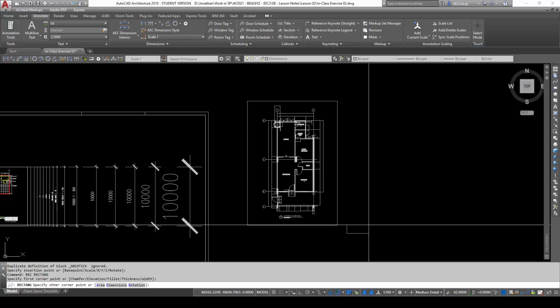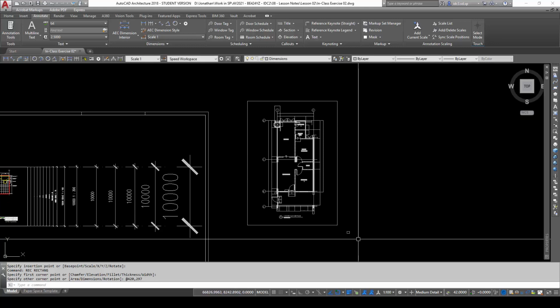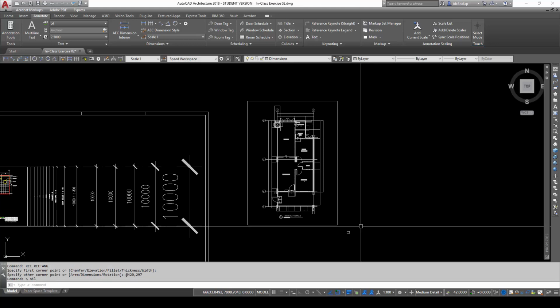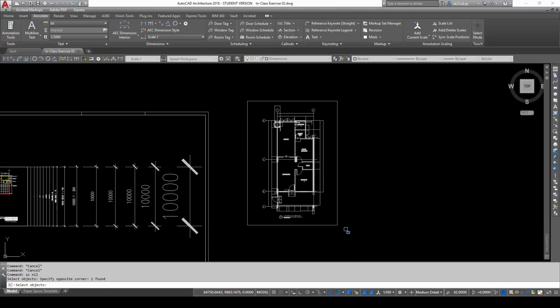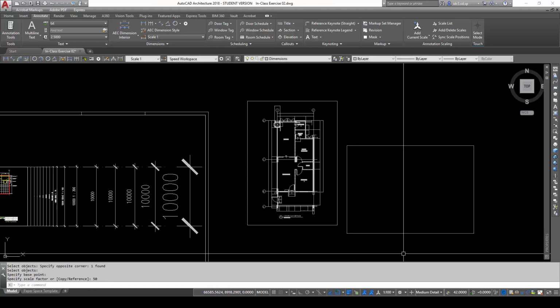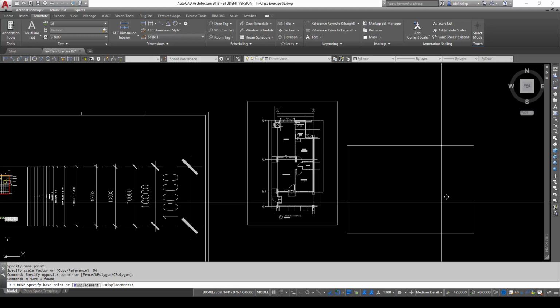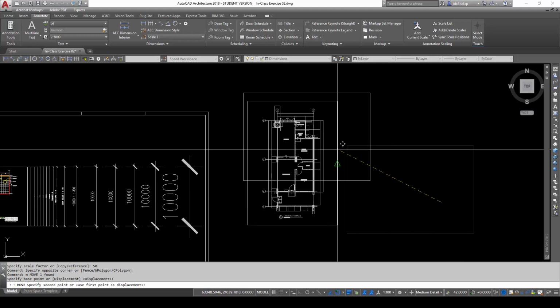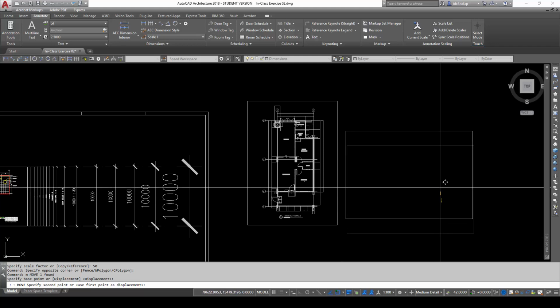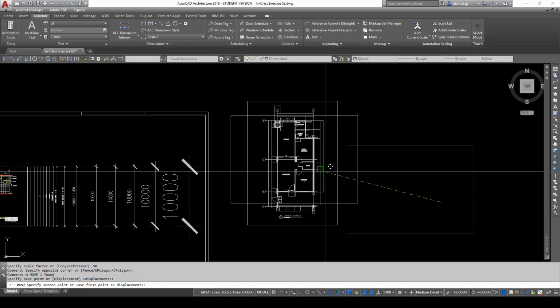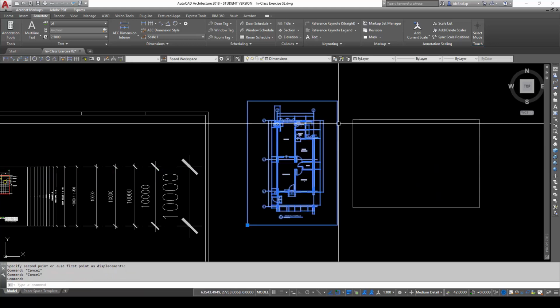And A4 makes it really too small to see details. So I'm going to just start with A3 size at 420 by 297. So this is roughly the size. So I'm going to just scale this one up. I'm going to scale this up 50 times to see whether we can fit this in quite nicely or not. Now obviously if you look at this, at 50 scale it looks very, very similar to the boundary that was given down here.